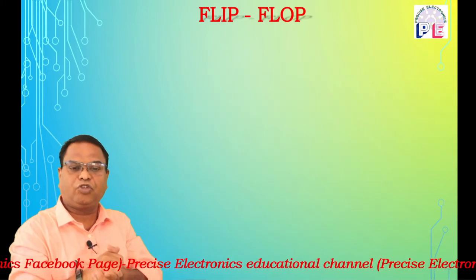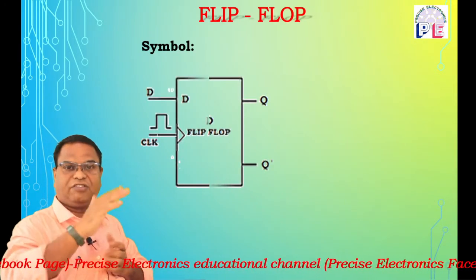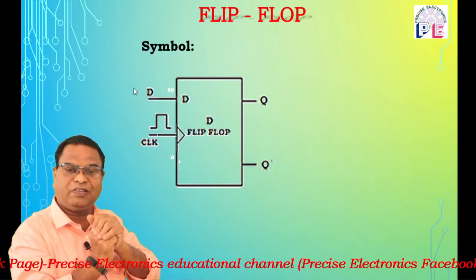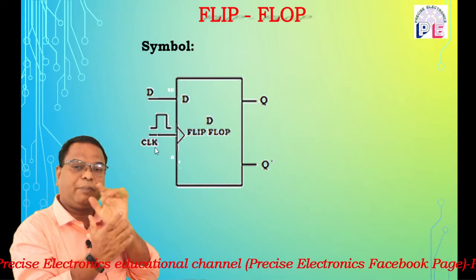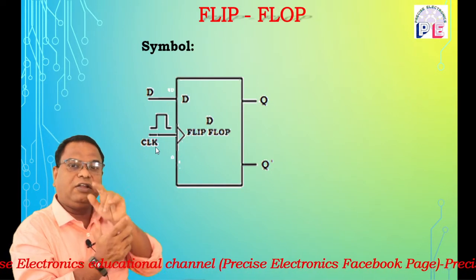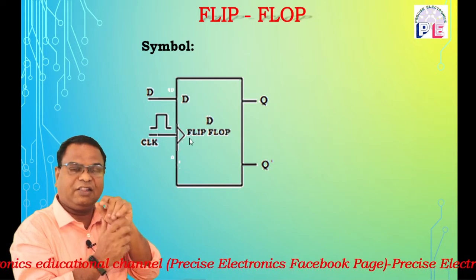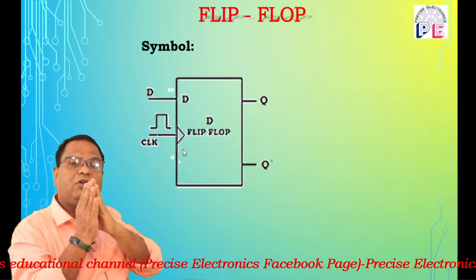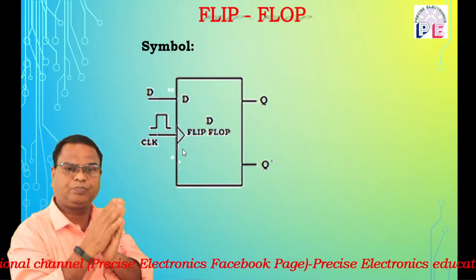The symbol of this positive edge triggered D flip-flop is now going to display on the screen. There is the data input D, and the clock pulse is applied. There is a clock input, and this clock input is applied to the flip-flop, and in that symbol a triangle is there, and this triangle indicates it is positive edge. It is an edge trigger, and it is a positive edge trigger flip-flop.